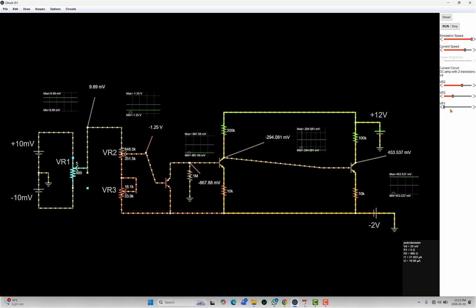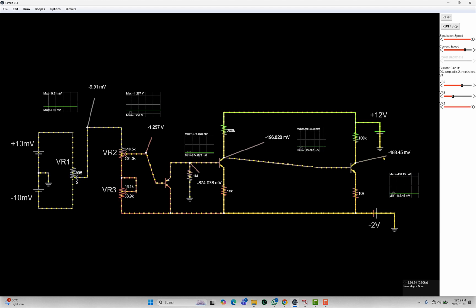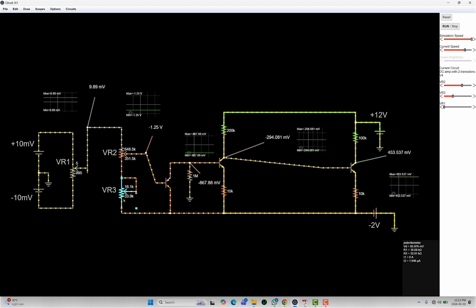And then I took that. So this signal, I took this and I pump it into here, and I balanced everything so I get the even swing here on this output. Right? So yeah, 488 to 453. Now these two resistors here, this is a 50K and a 1 meg, and I did this for fine tuning because it allows me a little more precision on that, and maybe even not quite enough precision. So that might be why I got some difference here.